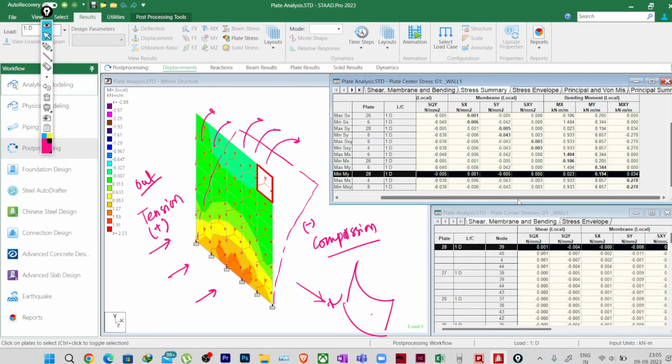So what you can do, you can provide minimum reinforcement in the other face, as there is no compression value, right? Correct. Actually this is what the behavior should be, because there is no prop. What I drew in the bending moment diagram will not be like this. I have drawn the bending moment diagram like this. It will not be like this; it would happen when we have a prop here. Actually we don't have anything here, so it's fixed like this. So the bending moment will be like this only. Okay, so the outer face will undergo tension like this. Correct.